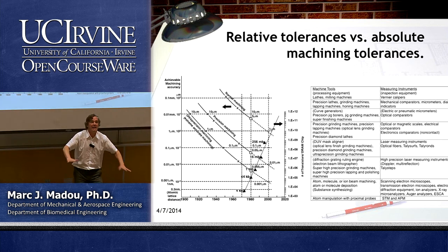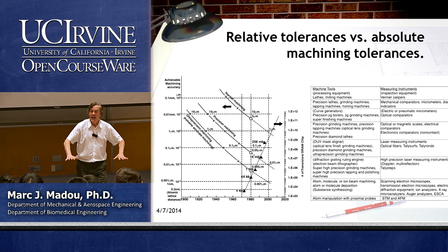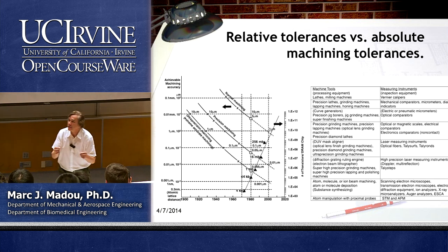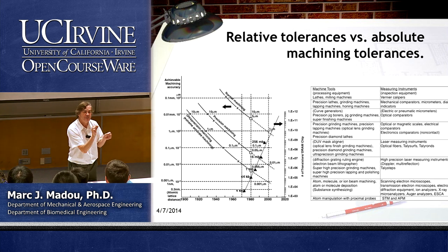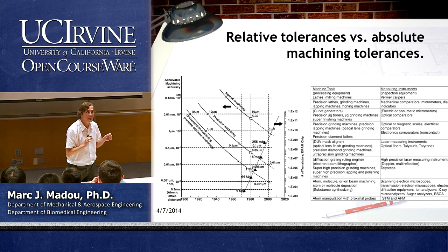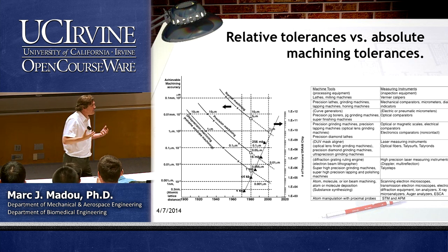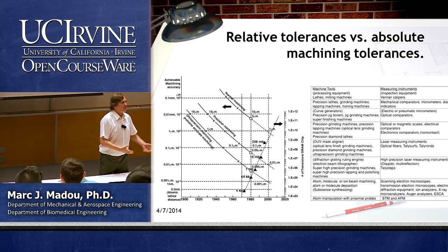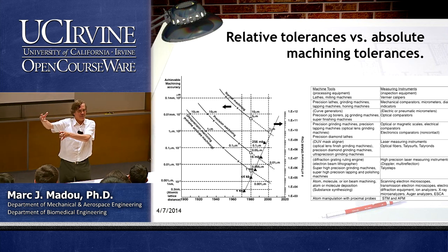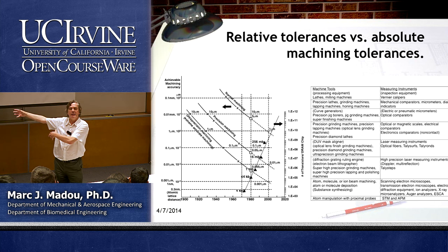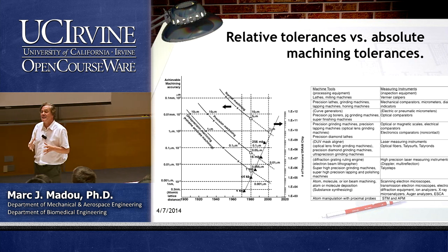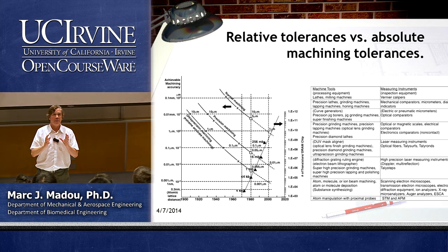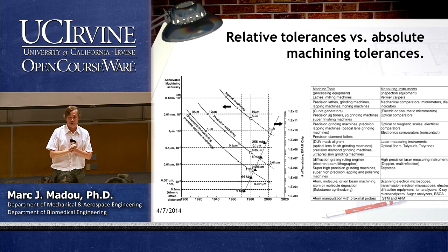We got rid of any vibration, we got air bearings, and the better we could control the smallest dimension change on these stages, the better product we could make. So there is not all that much difference, in a way, between integrated circuit manufacturing and mechanical machining, because both are grounded in the need of very good XY positioning stages.